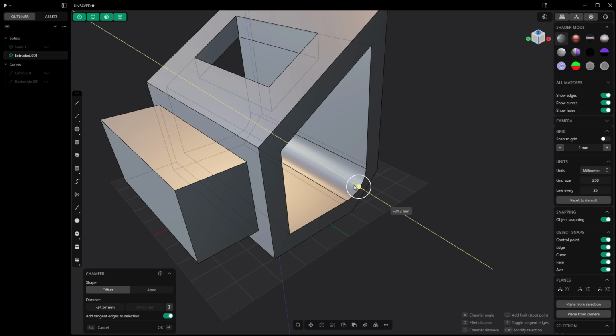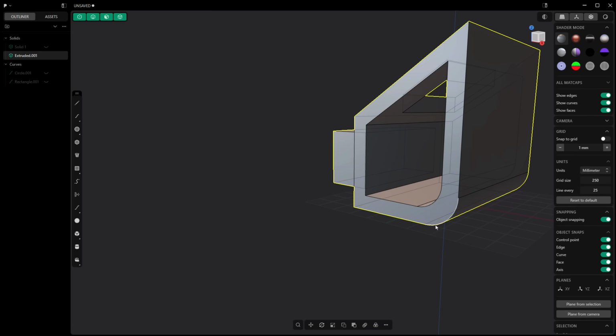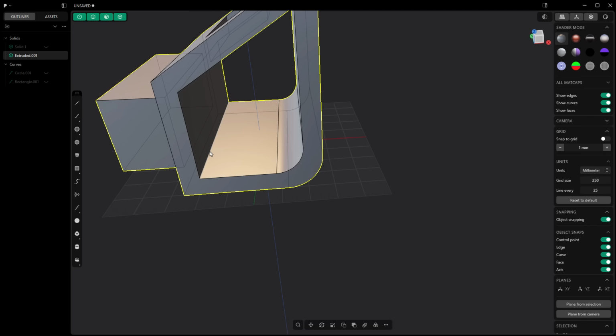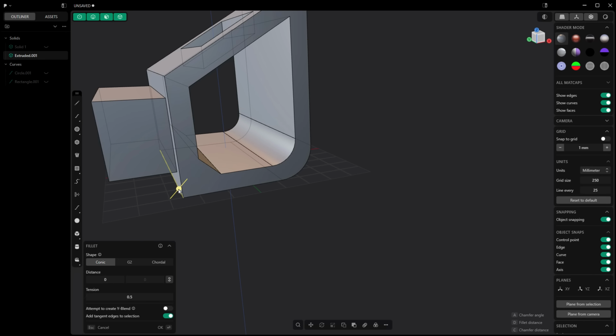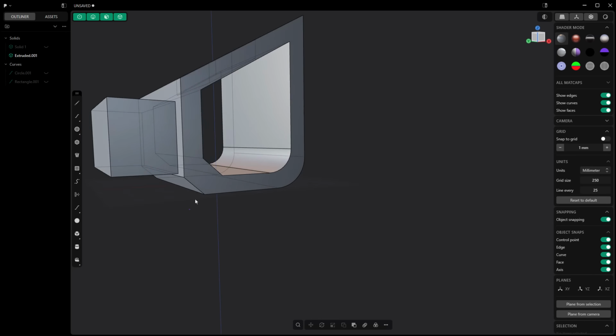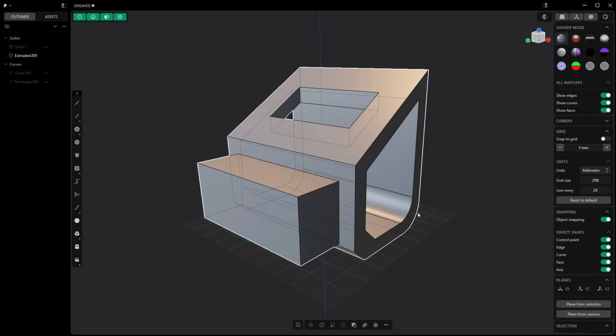However, a fillet on the outside is removing material from the design. So we're taking material away from an external corner, but we're adding it on an internal corner. And this is true for a chamfer. So on the inside, we're adding material. On the outside, we'd be removing material. But again, the same tool, the same general workflow, and that's adding or removing material from your design.